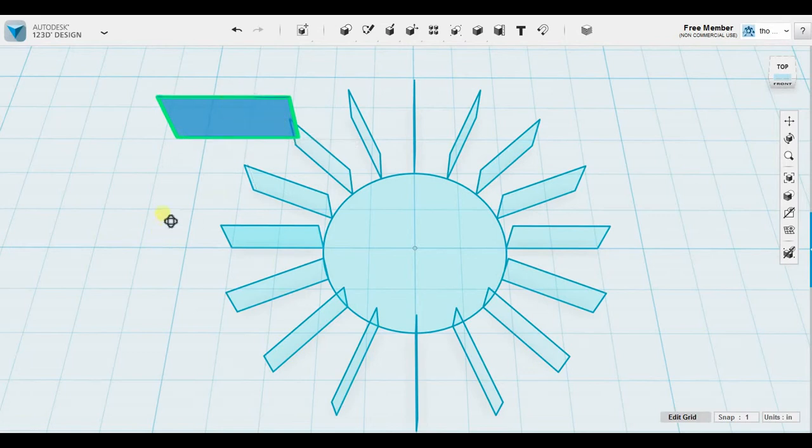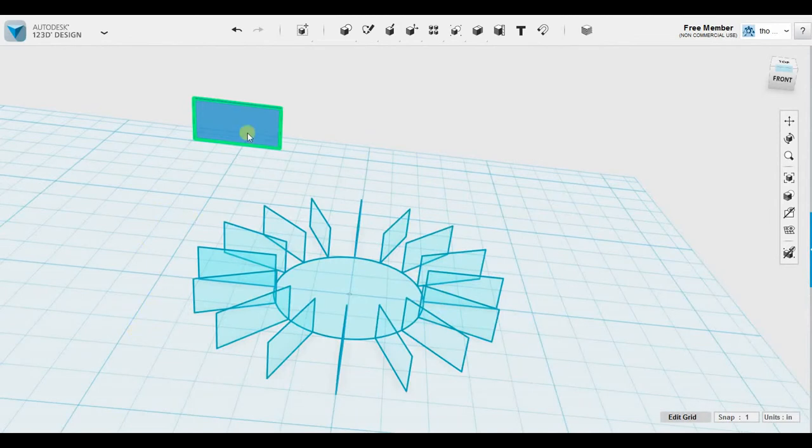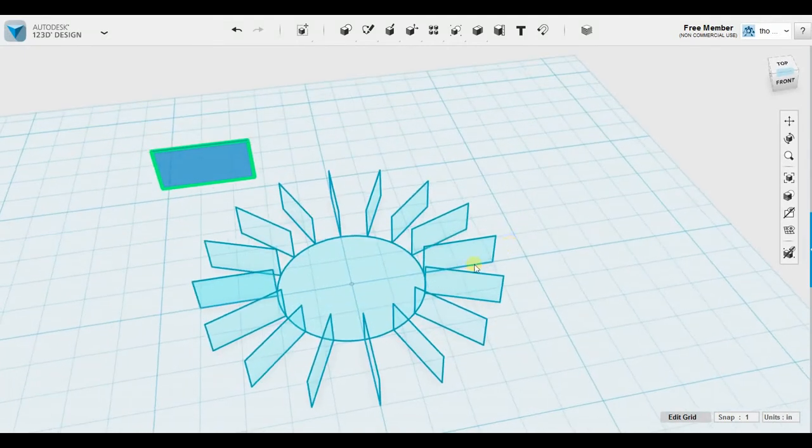There we go. So now I have to raise all of these in proportion to where at the end it is 1 inch. Meaning that since I have 16 of these profiles, I have to raise it up in 1/16 increments. So this first one I will move up 1/16, which a 16th comes out to be 0.0625.